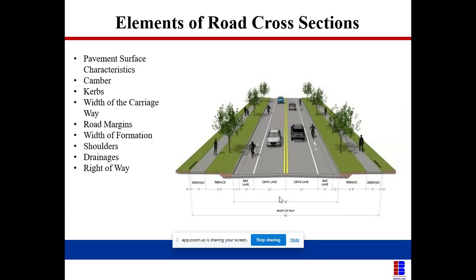So this is when all those things you'll be learning in the class periods will come into play. If I'm designing a road, I will do my storm analysis to know the actual size of the drainage that can cater for the runoff water coming from the paved surface. I'll design for them, analyze, and get the size of the drainage that will cater for the rainfall runoff water coming at that particular point I'm analyzing for.